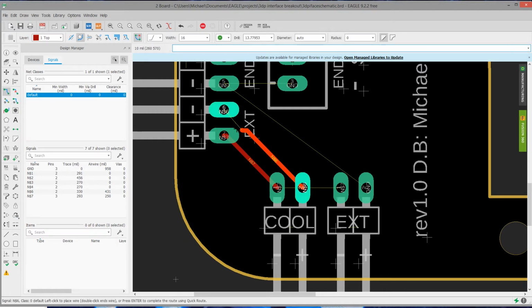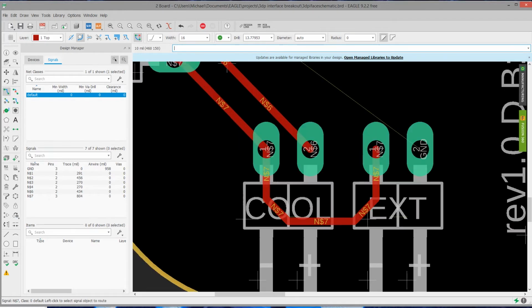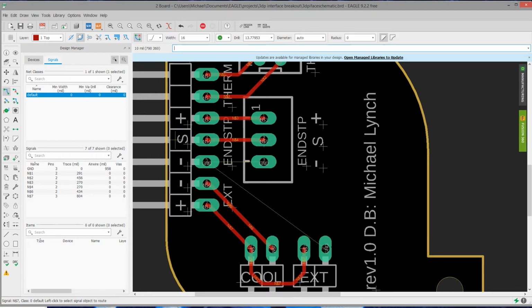Okay, so now we'll route this guy here. And yeah, for some weird reason, it just loves binging and making a bunch of noise. So kind of, there we go. So as you can see, as I'm drawing out these lines, we are removing these yellow lines here, replacing the red lines. Now you can also go switch to the bottom layer. In the free version of Eagle, you have up to 2 layers. I think in the paid versions, you can go all the way up to 16 layers, which for our design, there's no need for the bottom layer, so we're just going to use the top layer because that'll be the visible layer. And it's kind of cool to see the traces. I personally like showing them off at least.